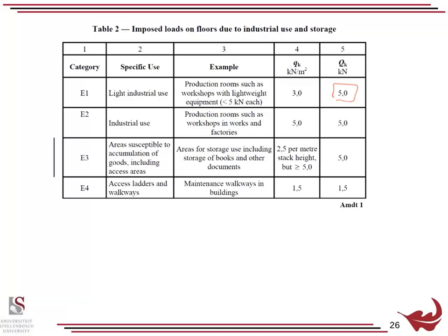They say, hey, that's a great place, it's concrete, we will now put our new switchgear or our transformer or some big piece of electrical equipment on top of that roof, which was never designed for any of that load. And we know of a case where they dropped a big piece of electrical equipment through a roof that someone else had designed, thankfully. From then on, we just over-designed all their roofs, because we knew at some stage in the years to come they would put something up there.